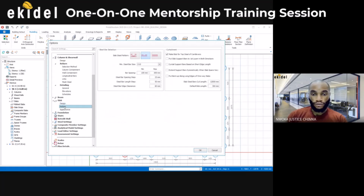You can see maximum spacing 300. I can say I want to use 200 as maximum spacing, and for minimum spacing, let me say I want to use 125. So you can set all this, and then minimum bar size D10.